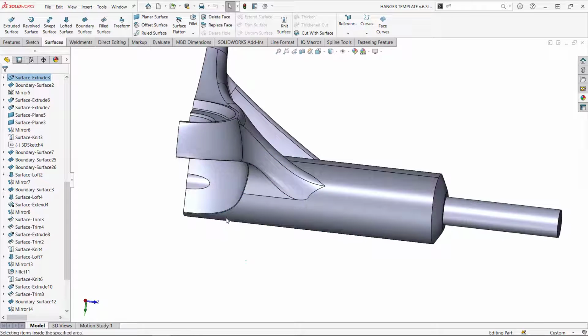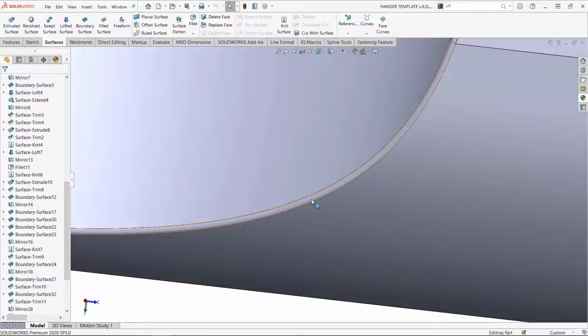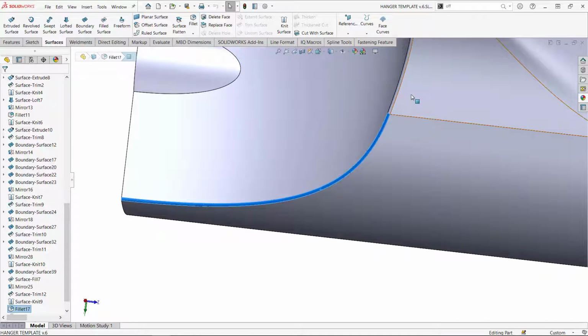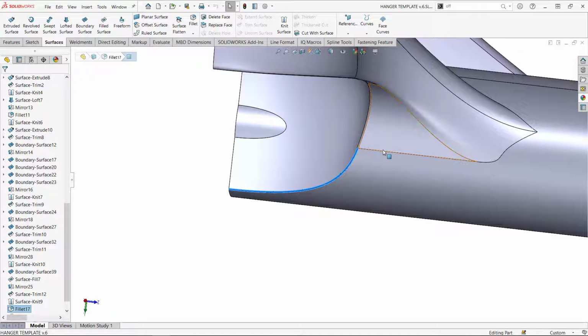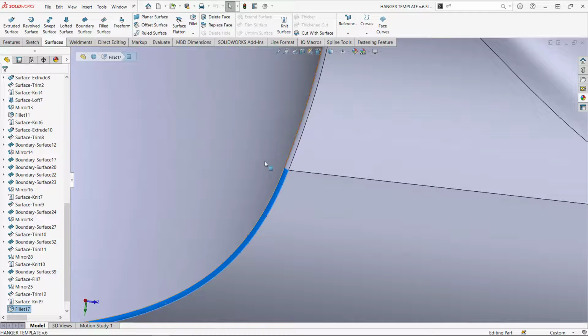First, though, I just want to have a comment. You can see there is a fillet at the back of these faces. So even though it's not apparently connected to the blend that we're going to create, it will actually be connected right here at the end. And this is going to create a big headache. So let's suppress this fillet for the time being.